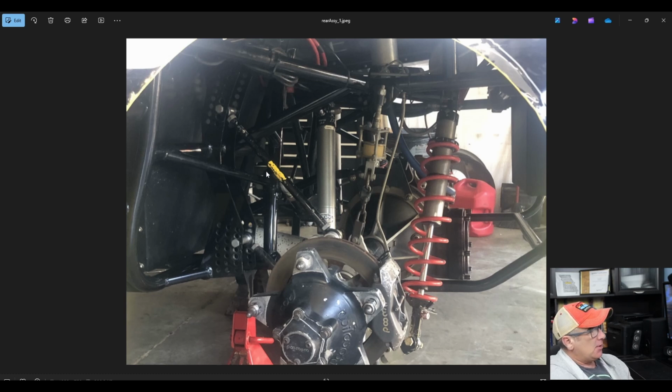And so what we have right here is an upper 4-bar link, and down here you see kind of the front end of the lower 4-bar link. Those two links are part of what we call a 4-bar mechanism. There are two other bars in this mechanism, and that is the chassis. So the chassis right here creates a bar out of that 4-bar mechanism.